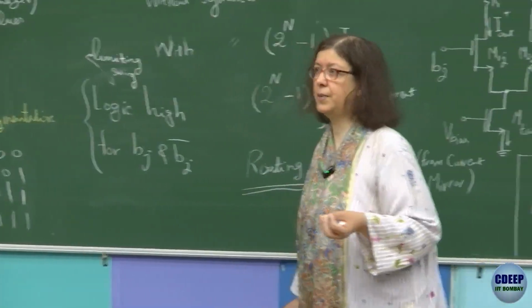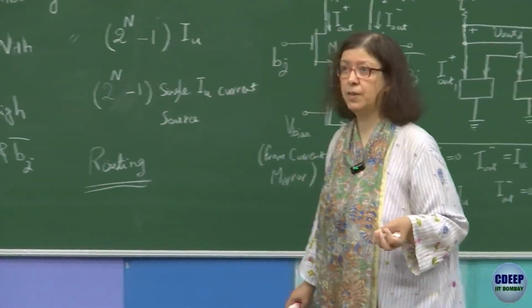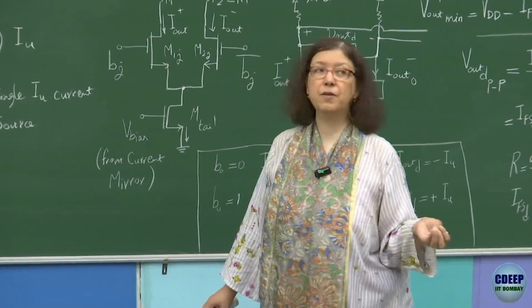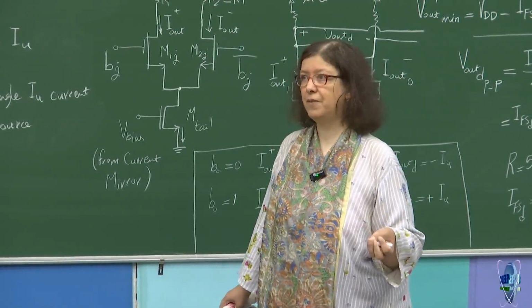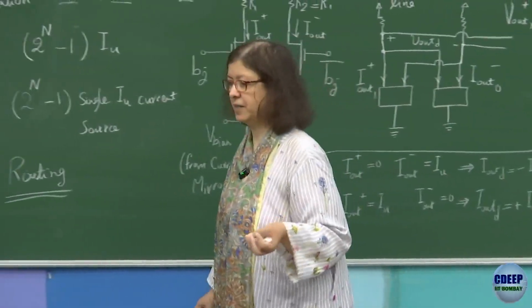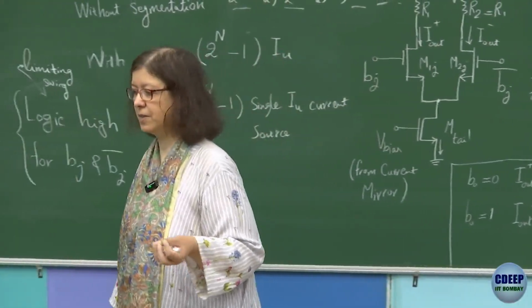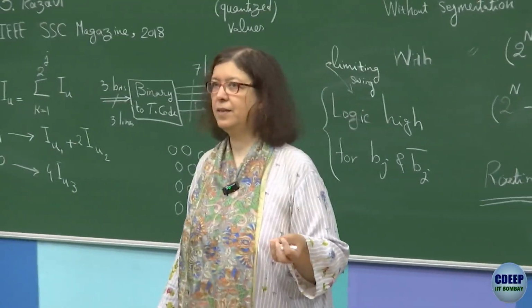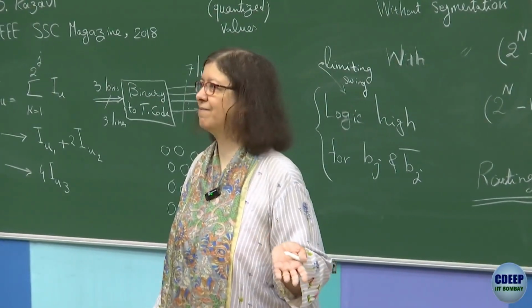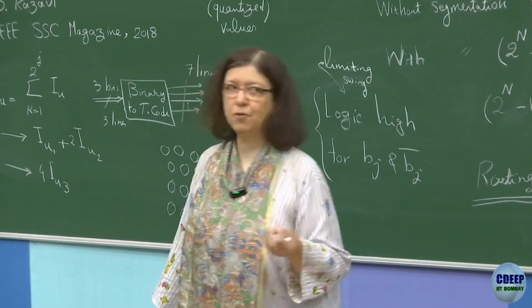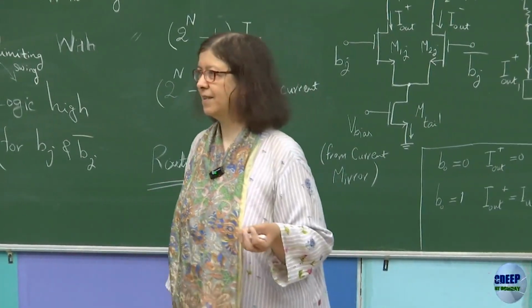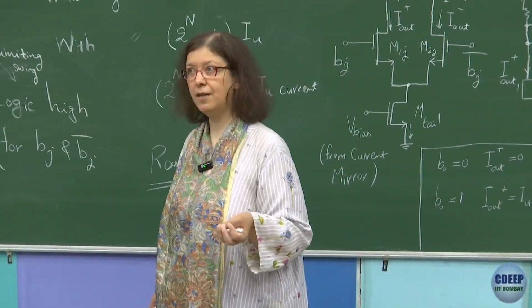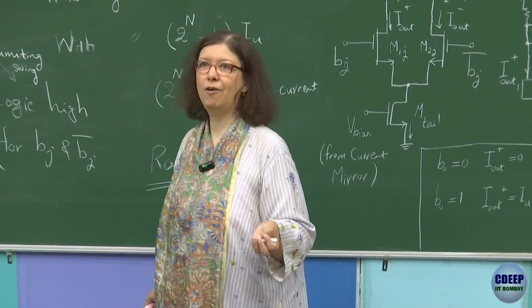In high speed, you deal with signals in the time domain, which can have many frequency components, but they have to be fast enough. One example that high frequency doesn't always mean high speed is the slewing in op-amps. A very wide band op-amp is not necessarily fast, because there are large signal effects which make it slow.